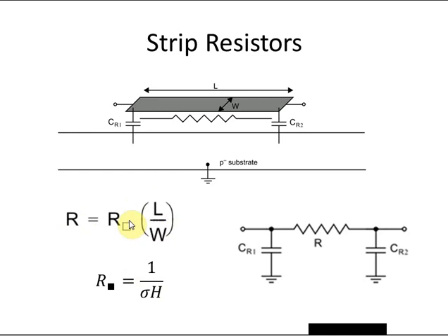Generally, when you're laying out resistors, you're not going to want to make W very, very narrow, for example as narrow as is absolutely possible in a given manufacturing process, because doing so will make things like the surface roughness, the edge roughness of the conductor, dominant considerations in the variability of the value of the resistance. So usually you would make it considerably wider than the minimum that's possible, and then, of course, the length would have to increase proportionally to get the same value of resistance. That gives you a tighter control on the resistance. Often you're going to be laying down more than one resistor next to each other, hoping for some matching between those values, so making the resistors a little bit larger helps in that regard too.